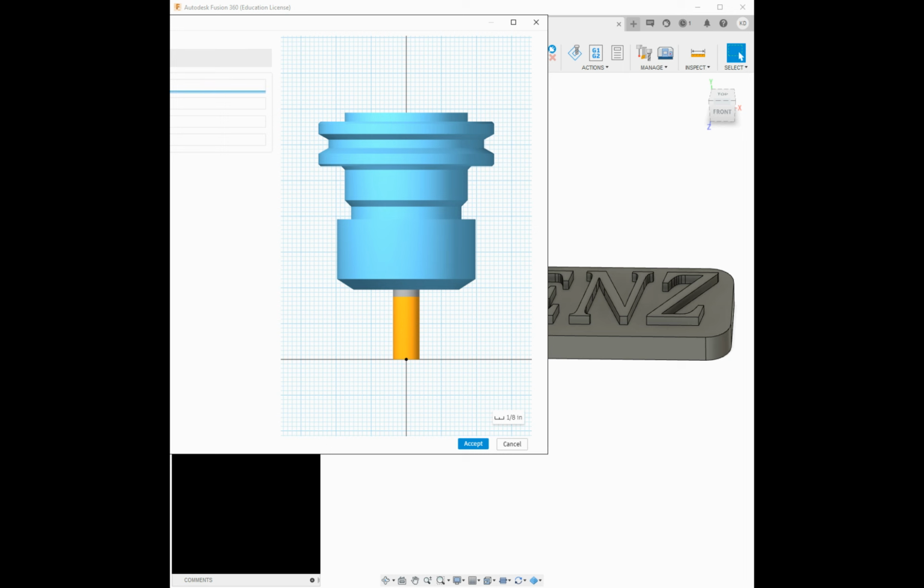First of all, name it exactly what you need so there's no ambiguity later. 1/8 inch flat end mill. We'll do a 1/4 inch next. We're going to navigate this tab and change everything that we need to. For cutter, we could change it here, but we're going to leave it flat end mill. So really, you can pick any type of cutter and change it. I don't know, I just find it easier. That's a habit I have, is trying to select something close first.